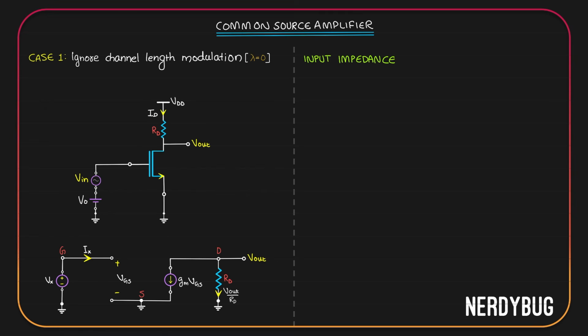It can clearly be observed that the circuit is open between these 2 points. That means current Ix cannot flow. Vx is the potential dropped across these 2 points. Since the circuit is open between them, we can say the resistance between these 2 points has to be infinite. That makes sense, but it is not entirely true. Because we actually can have some capacitance between these 2 points. And that will give some capacitive reactance.